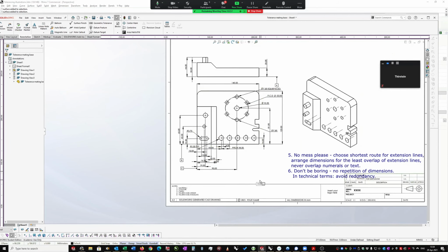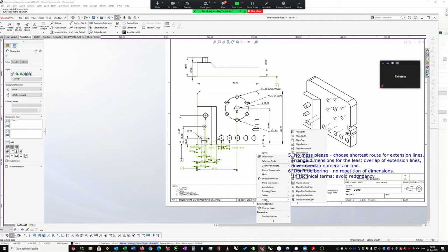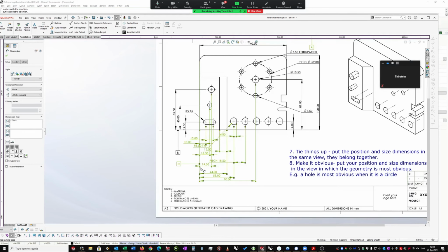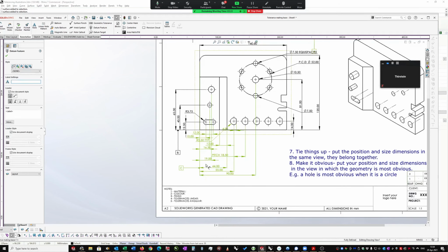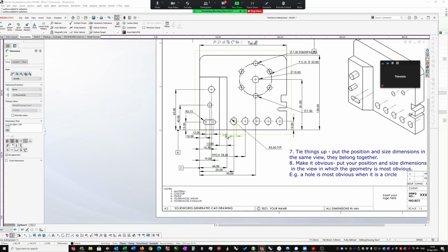Then to organize all of this, I just drag, select from left to right, right click, go to align, go to auto arrange, and it'll neatly space things out. If I'm not 100% happy with it, I can just move things out of it. Oh, and my computer is just slowing down radically. But it'll place the dimensions for you from largest to smallest. And you can then rearrange a little bit. So make it as neat as you can and as equally spaced as you can.